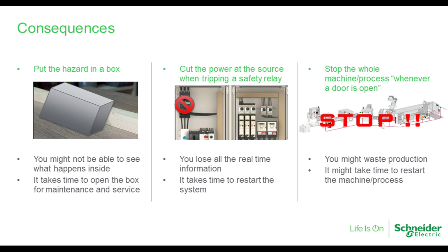So now looking at the second point, when it comes to killing power, pretty easy to see what could happen here is that if you're dealing with automated machinery, if you remove power, you also remove your communications. If you're doing some kind of logging or tracking of the status of the machine, operating it, you lose control. So that's not very desirable. Plus, you might have wasted materials because you're not controlling the shutdown, and then you need to restart it. And depending on what sequence of operation you were in when you had this complete removal of power, it may not be convenient to restart. It's going to be expensive in some way.